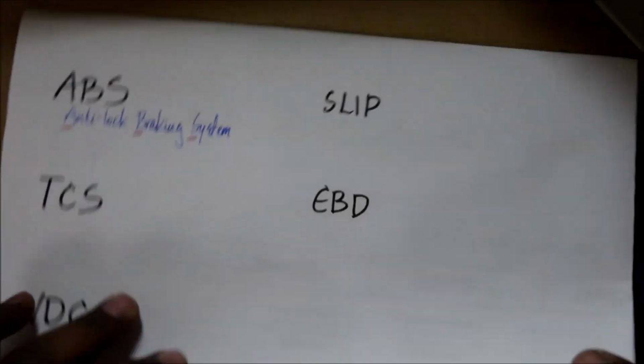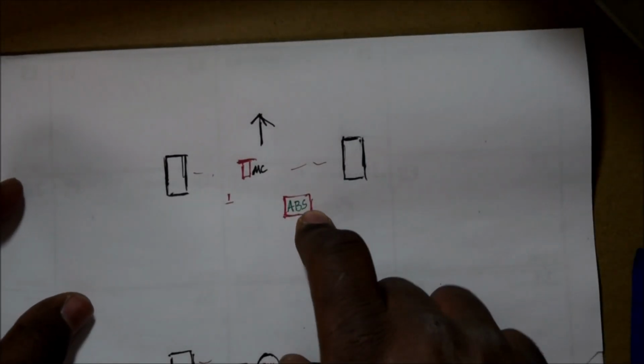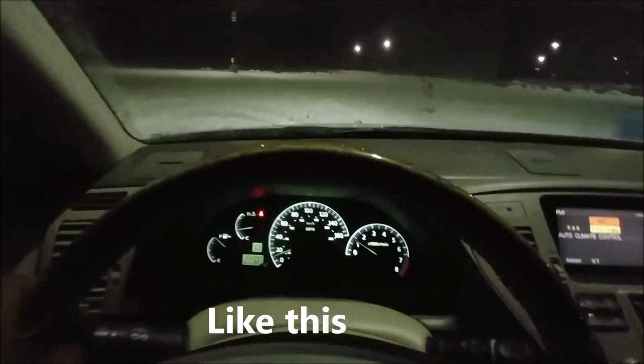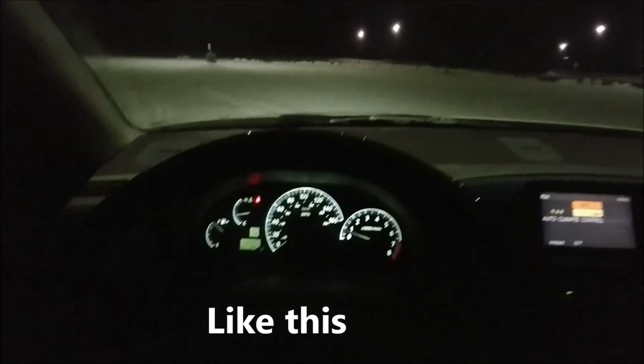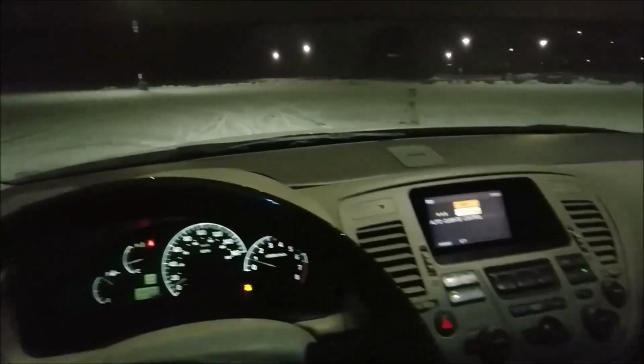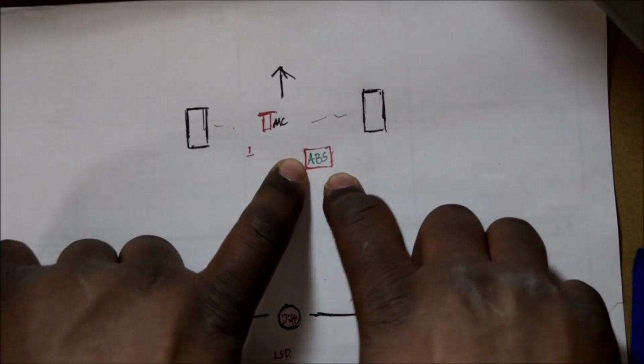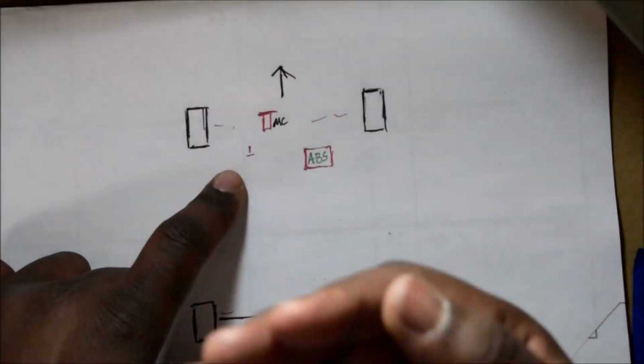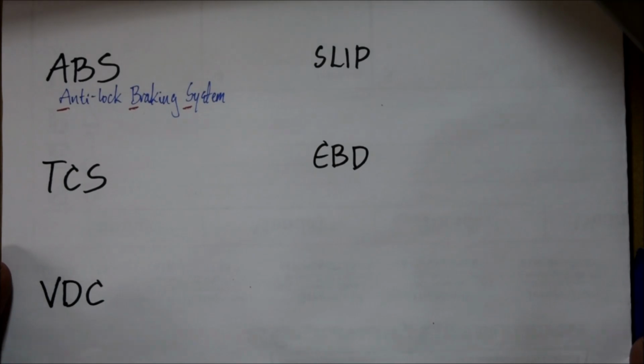release. You will usually hear this ABS module making mechanical noises like vibrating, buzzing. Also, because the brakes are being applied aggressively, you might hear some slapping noises. That is due to the brake pad being slapped against the rotor. Not only that, because you have fluid kind of dancing around in here, your pedal might vibrate as well, pulsate as well. So those are the things you'll see when it's in operation, right?